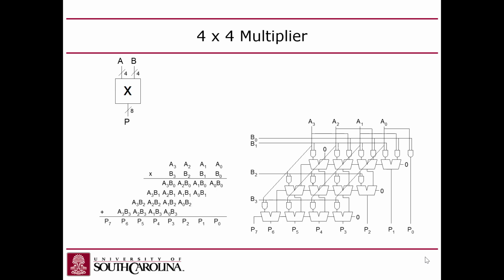So, an AND gate is kind of like a 1-bit multiply. Make sense? So they take A0, A1, A2, A3, and they put these AND gates, which they AND with each of the corresponding bits of B. So A0 gets ANDed with B0 here.